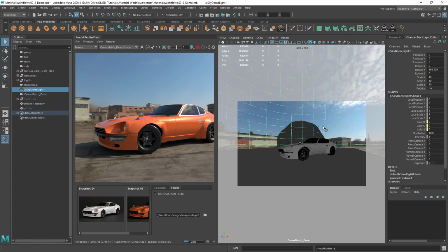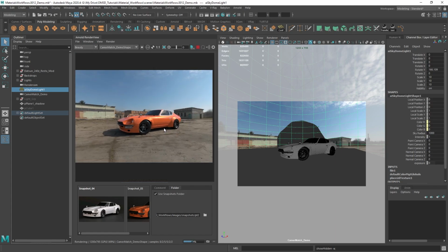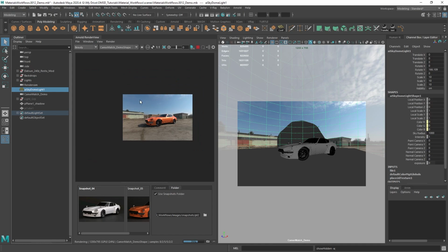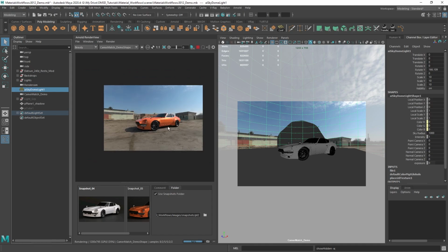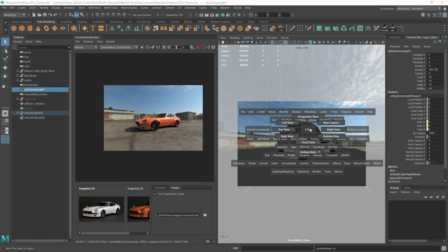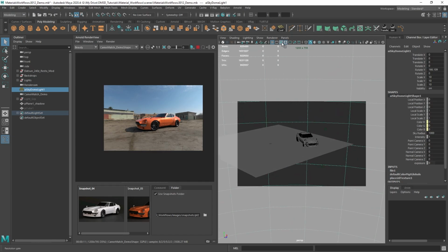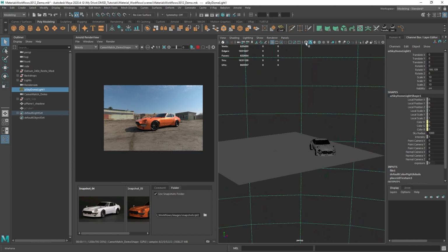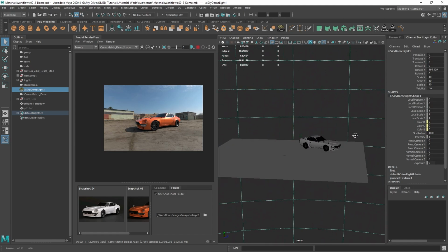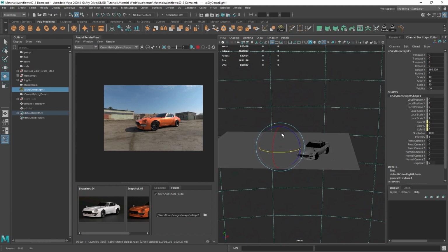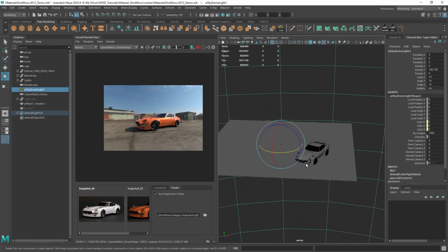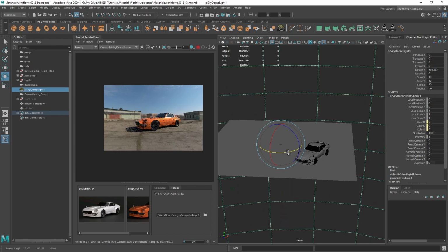And there we go. So we're getting this now with this vehicle that looks like it was actually in this environment. Now, keep in mind, this is the HDRI here, but it was shot in a pretty close position. And when using image-based lighting, if I switch to my perspective camera now and turn off my resolution gate, because I won't need that here, and look at this, I can rotate my dome light now where it actually lines up with what's in the background.